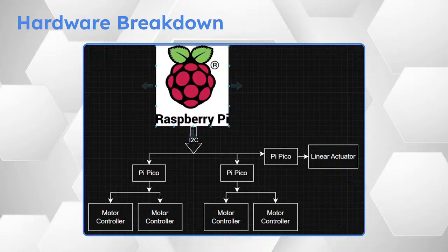I don't see a need to try to have 2 controllers. 1 should be fine. So setting up speed controls to Pi Picos. The Pi Picos can handle the RS-485, or the motors are also able to run on a simple PWM signal, depending on how much information we want to get back. That'll be a little bit of testing once we have the motors in front of us to see what the speeds and relative difficulty of all those are.